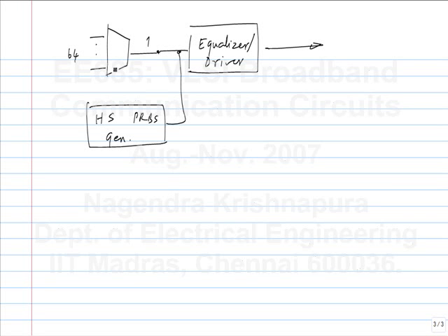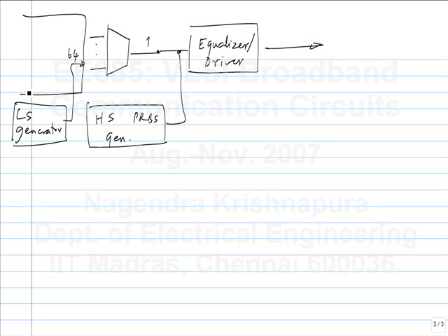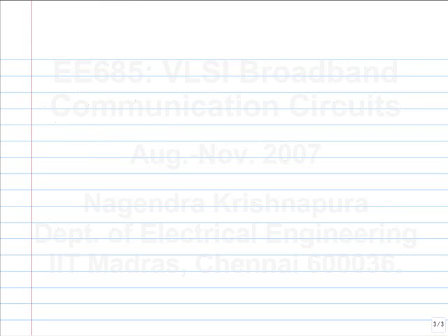Instead, you already have the MUX. So what you can do is, if you can make a low-speed generator, shift it appropriately and apply it here. Typically you have some other digital circuitry in this part, so you can use that to do a lot of this. So a low-speed generator consumes less power, but of course it has more flip-flops, so it can potentially consume more power. But you are using part of the same hardware, especially the high-speed hardware. So that's the advantage of that. Any questions on the first problem?